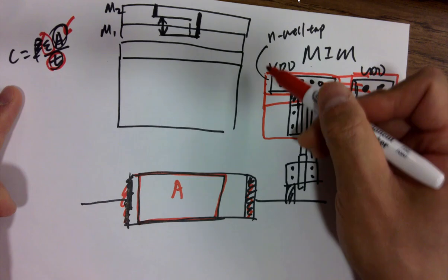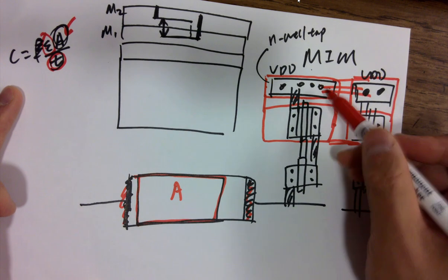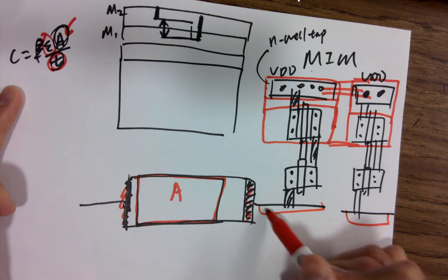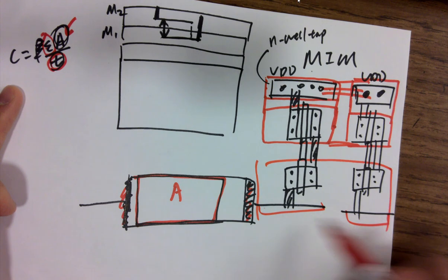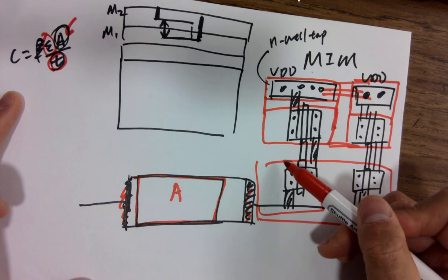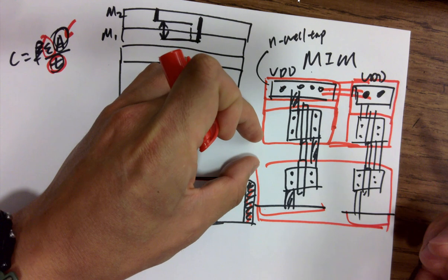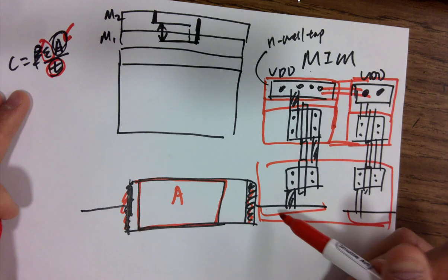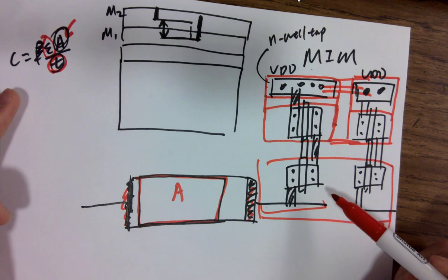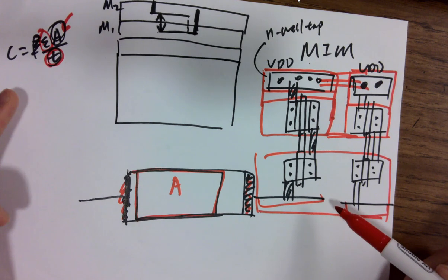So when you do the quiz, if they have the same N-well, you want to draw it. Same here. You got all the P-well taps, and you want to draw a universal P-well to cover it. And there should be a gap in between. Keep in mind, these shouldn't overlap. And do you really have a P-well in your electric VLSIs, the C5 500 nanometer technology? Is there really a P-well?